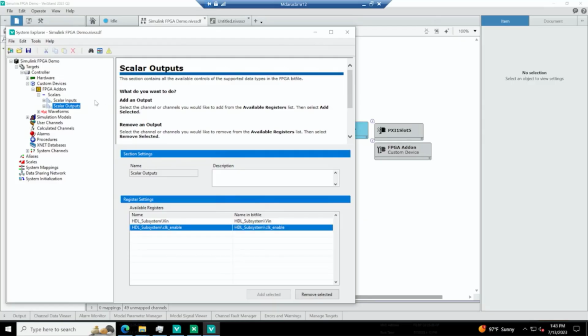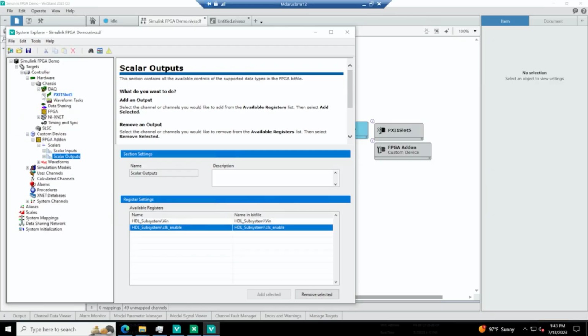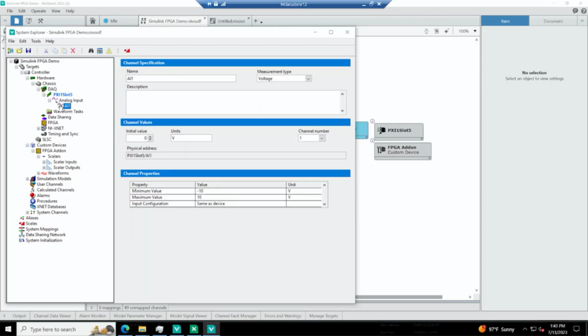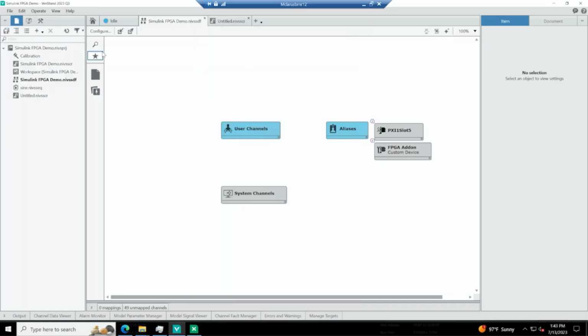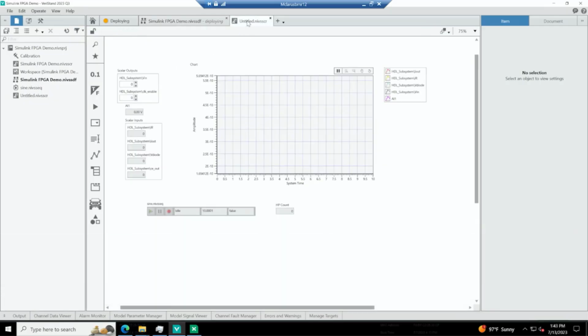The reason why I selected that one analog output in my model is that it's actually going to be looped back into a DAC analog input just so we can test in this case and show that, yes, I actually am receiving that signal physically. In the real world, I'd be sending that signal out into my DUT itself. So similarly to the engine demo, I can now deploy this down to my target and get ready to see responses on my screen.